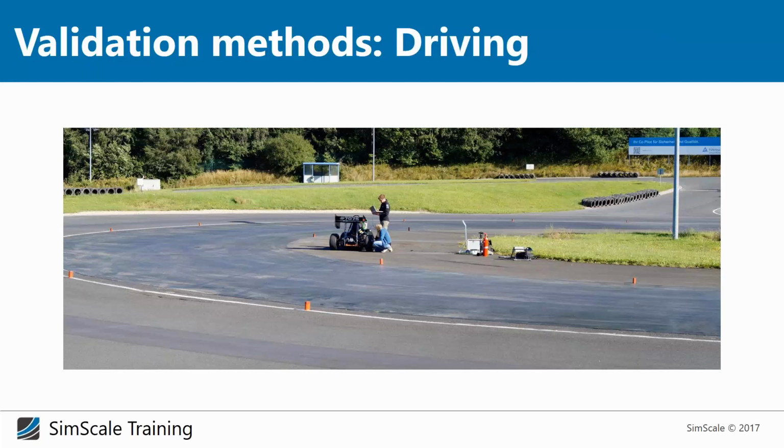And the last but most simple method is just driving. Set up a really simple course with maybe one tight corner, a long straight, and one corner with a big radius, and then let your driver just drive like 25 laps with aero and 25 laps without aero, and do this with 2 or 3 drivers, and then just compare the lap times.